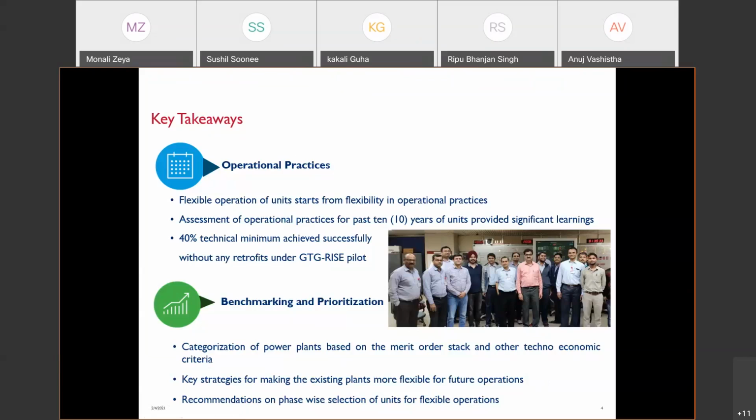For example, whether the machine on auto mode and manual mode has already given those provisions for operators, whether bypass valves should be used, whether the flame stability can be managed through burner tilt mechanisms or advanced flame adjustment mechanisms, how the coal mills should be run at an optimum load so as to ensure flame stability.